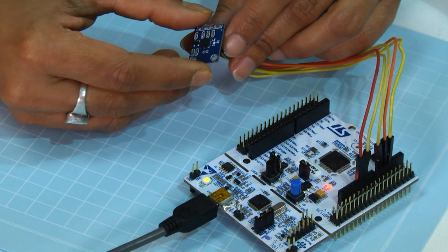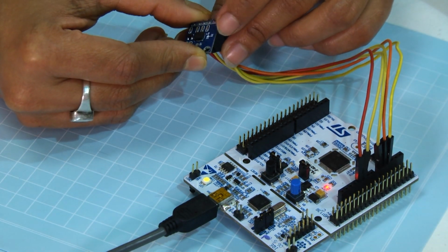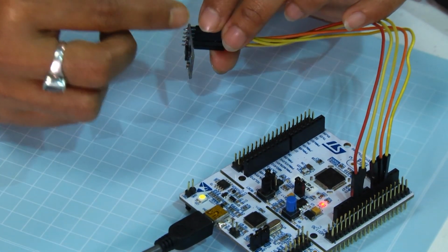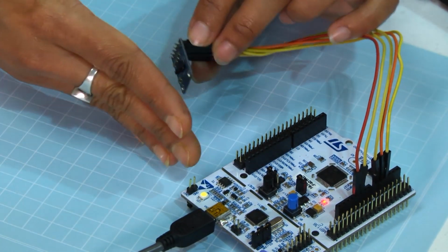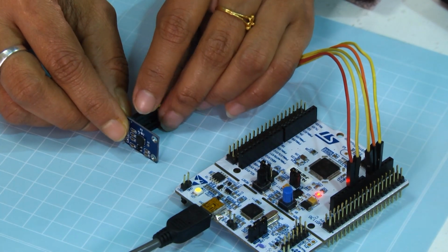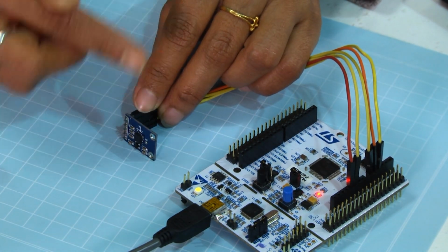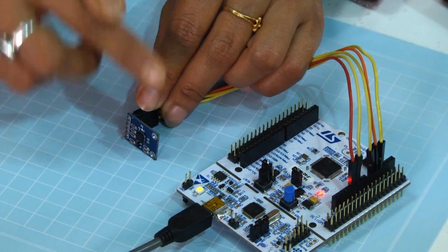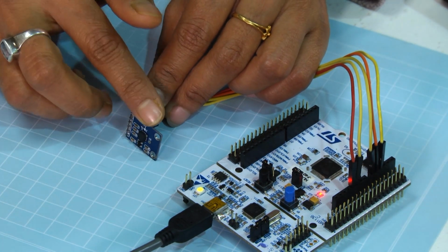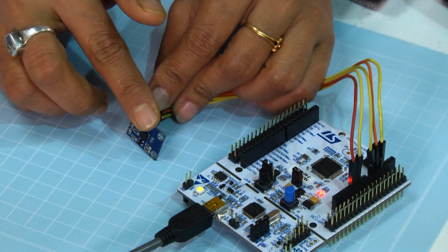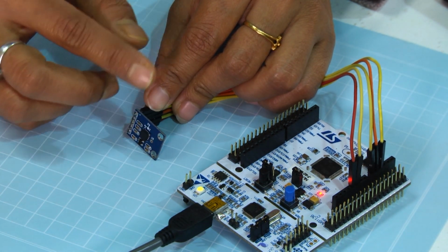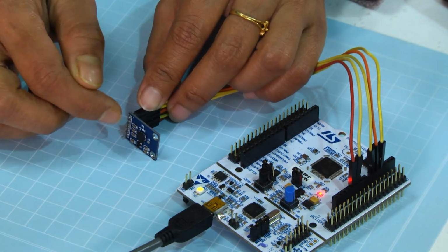So, you can make sure that the x axis value should be high, such that you have put up this accelerometer in that application in such a way that x axis is like this. If it is like this, you will receive the highest x axis value, and if it is not the highest, and the other two values are higher, then you have to make sure that your device is not properly placed. Okay. So, some kind of alert may be given that the device is not properly placed.